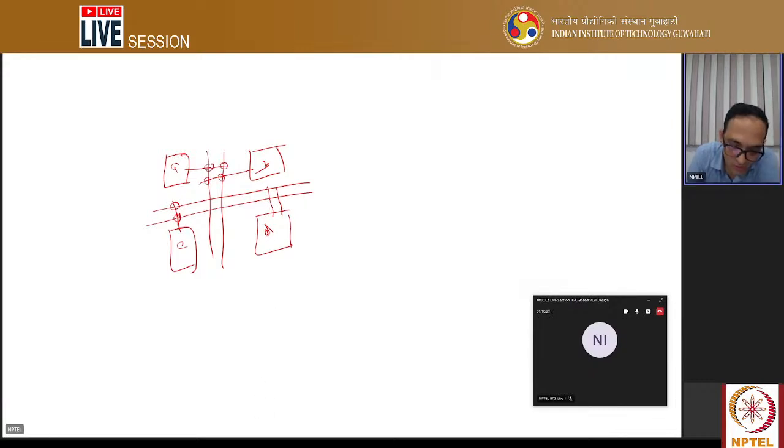Here there is no switch, which means they are not connected. They're just two different things in two different layers. Suppose this is wire X, Y, and this is W and V. X and V have no connection because they are just in two layers. I'm trying to give you an idea. Now every switch has a bit. This is what you effectively generate in FPGA: the bit stream. For every switch there is a bit.